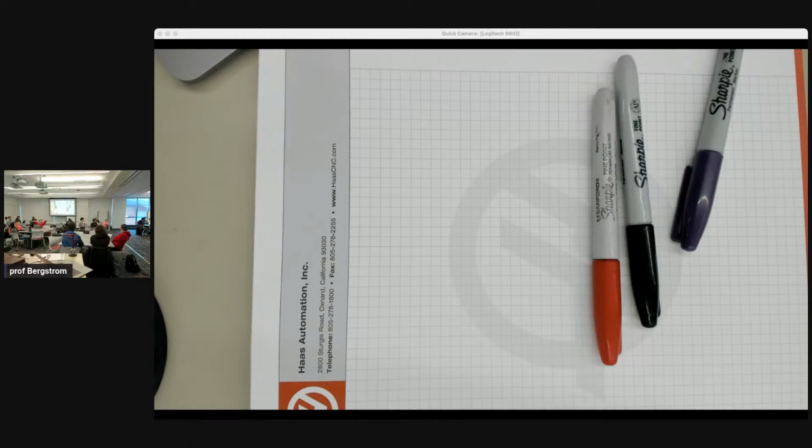There is some flexibility in the order that you do the steps, but you have to do all the steps. So you have to set the work offsets, and that's part of what we're going to talk about in today's class, what happens physically when you set the work offsets. But the overall is setting the work offsets tells the machine tool where the work piece is relative to where the 0 is that you set when you created the program. So we set the work offsets. What else? Yes. We do check the distance to go, and hold that thought because I'm going to do that one last. Okay. We set the tool offsets.